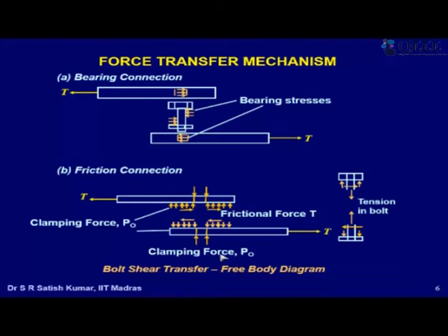So my nut has become loose, so I can further tighten my nut by one pitch. One pitch is the 360-degree turn of the nut, so that nut moves by one pitch along the threaded part. That means I have developed that much pre-tension, equivalent to the amount of force I would have applied to pull the bolt and make it elongate by one pitch length. That is the tension in the bolt.